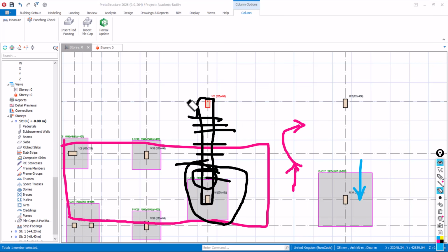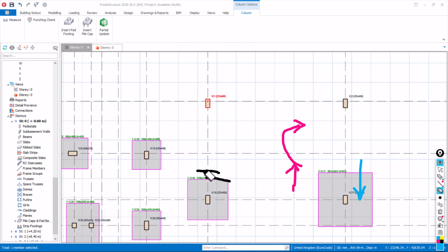So it will act as a counterweight to this eccentric footing, to take care of all the weight that we are experiencing here. It will also help to give uniform soil pressure around the bottom of this footing. Okay, that is fine. So that now gives us room to model our footing properly. Let's now go back to first of all insert our eccentric footing, and then come back to do our proper engineering design.